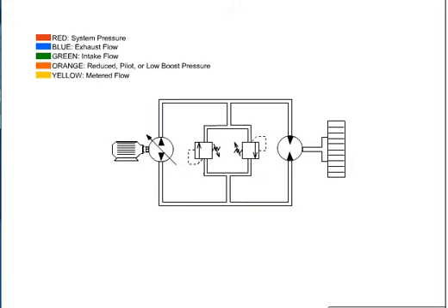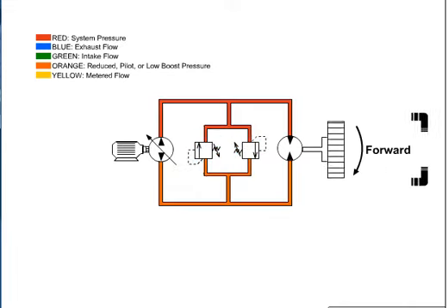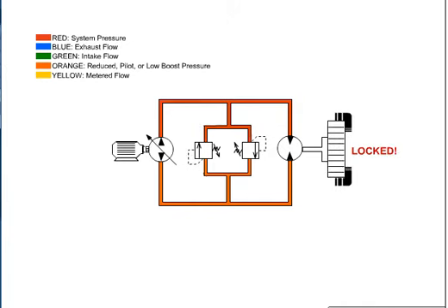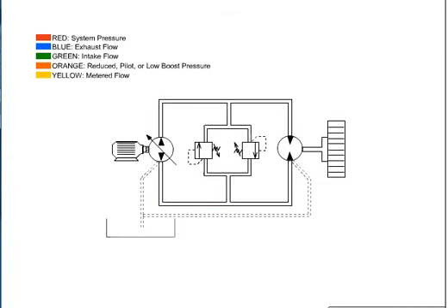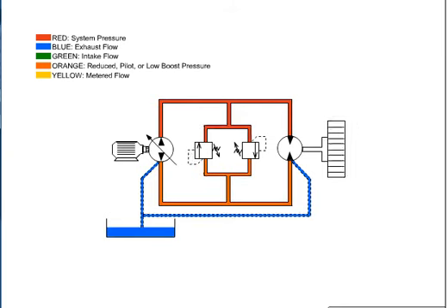In this circuit, two pressure relief valves are added to protect the system from overpressurization. When the hydraulic motor rotation is restricted or stopped, the high pressure relief valve opens and protects the system from overpressurization. This circuit adds a small tank to hold the leakage from the pump and hydraulic motor. This leakage must be replenished to the closed circuit.